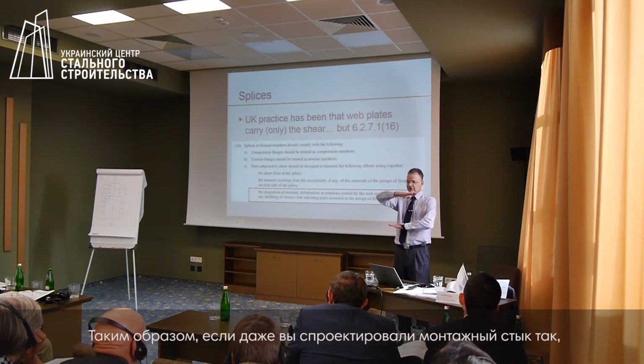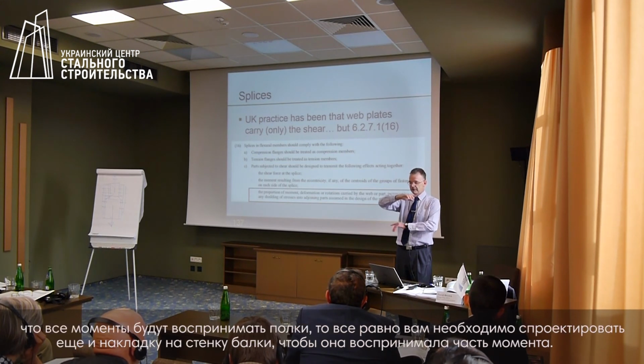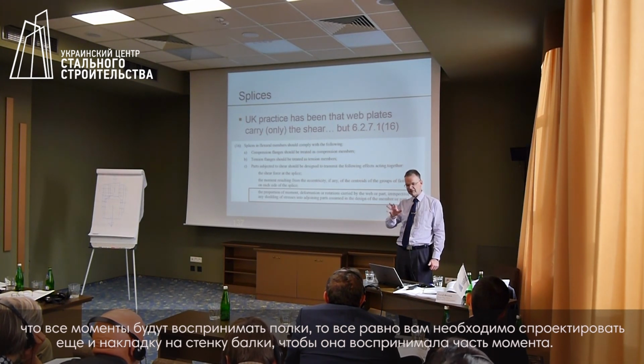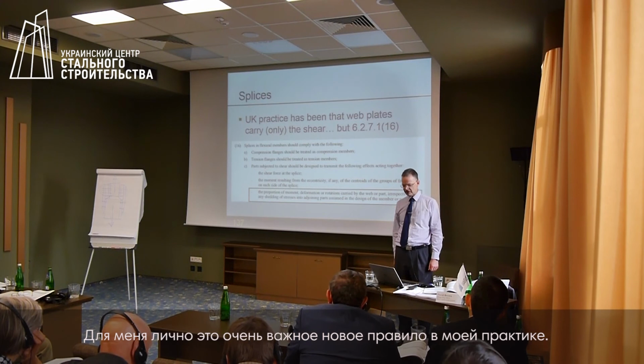So even if you have designed the splice to carry all the moment on the flanges, it says that you must design the web plate not only to carry the shear, but also to carry the moment associated with the web. For me, that would be an important change in practice.